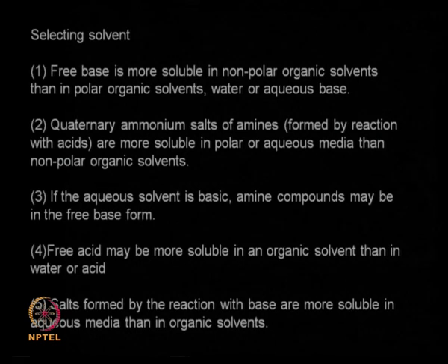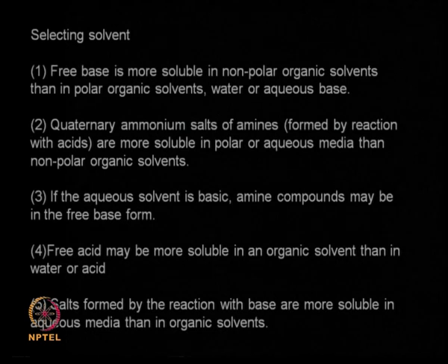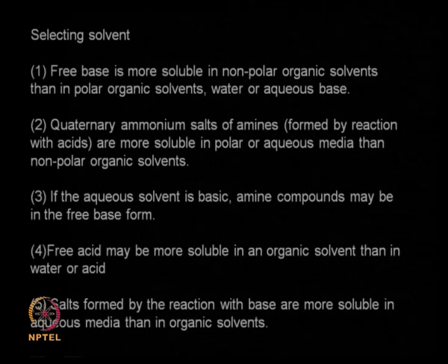Selecting the solvent plays a very important role and it depends on the type of product which you are trying to recover. Number one, it depends on the pH conditions of your fermentation broth, and it depends on whether it is an aqueous or a non-aqueous situation. For example, free base is more soluble in non-polar organic solvents than in polar solvents like water or aqueous base.